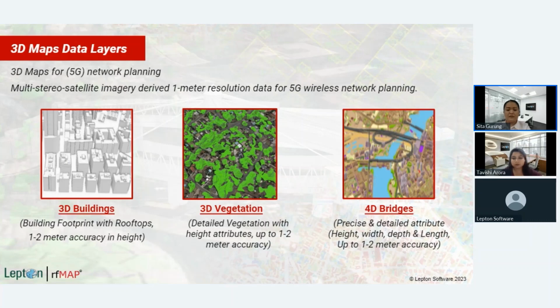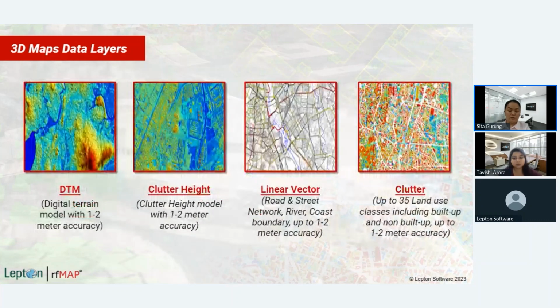Fourth layer, DTM, digital terrain model, which will have the information about height from sea level, and it's basically bare earth surface height, which means if you remove all the buildings and greens from the earth surface, that's the height information that you are getting. And in the telecom industry, the very popular term that we use is, with DTM you are going to get MSL value.